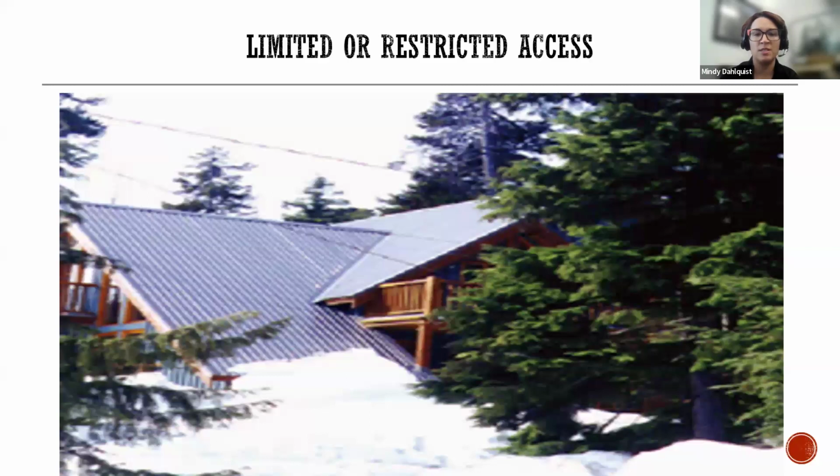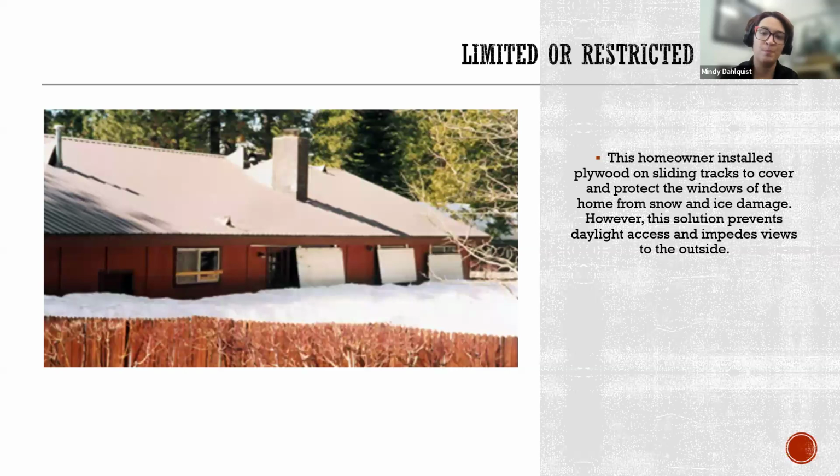This cabin was built with snow shed in mind, so let's get that snow off of this roof, allow it to shed. Unfortunately, the afterthought there was the beautiful walkway that was designed between the parking below and the large front entrance to the right. And so with inability to walk through your gorgeous walkway for possibly 4 to 6 months out of the year, it kind of takes the joy out of the beauty of the walkway. So always considering if you are allowing that snow to shed where your walkways, windows, doors, garages, all of those things are, is going to be very, very crucial.